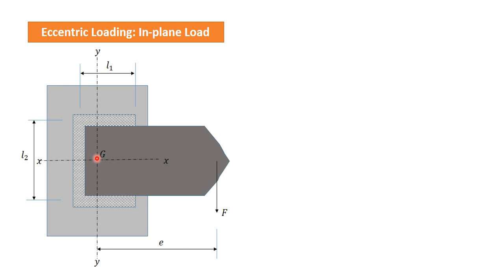The same procedure we have done in the eccentrically loaded riveted joint and bolted joint. In all those cases, we shift the load to the CG of the bolt geometry, and then we find what is the effect of that load.